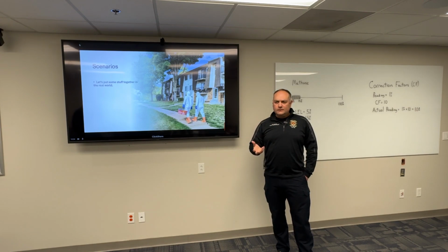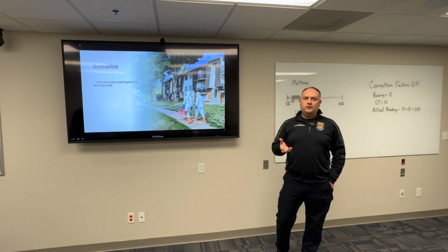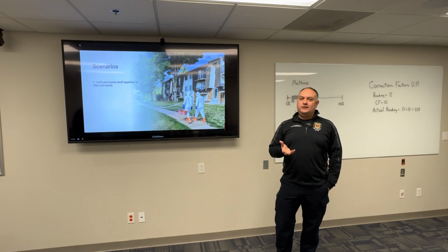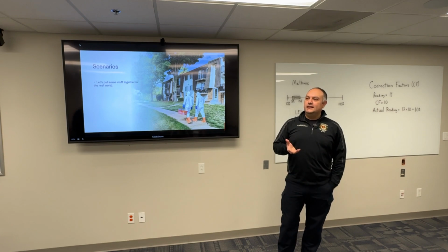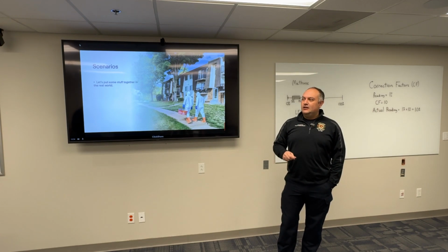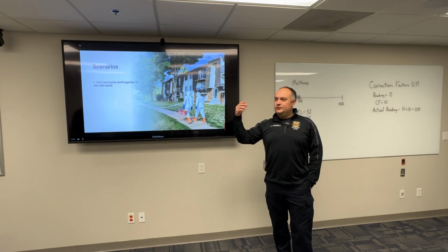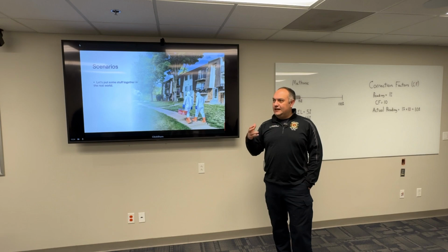So just something that's, like we talked about before, consider alternative sources when we're talking about CO. It might not always be the furnace. It might not always be the water heater. It could be something as simple as, oh, I left some stuff in the oven, some plastic stuff, and it actually charred, but it actually put CO throughout the whole building. So that was my scenario.